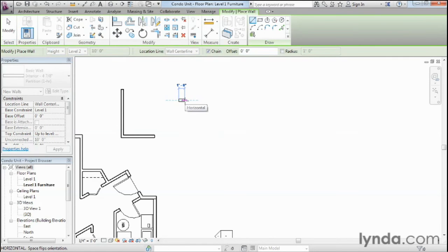and show you what you would want to do here. Now, of course, you can focus on the snapping behavior that we talked about a few moments ago, but as we said, we can type in. So what if I wanted both feet and inches? Maybe I want this wall to be 5 foot 2 inches long. Well, you can type this exactly like AutoCAD.